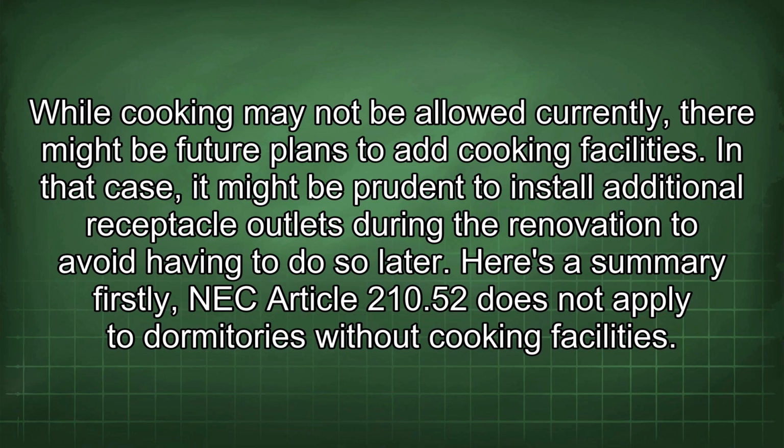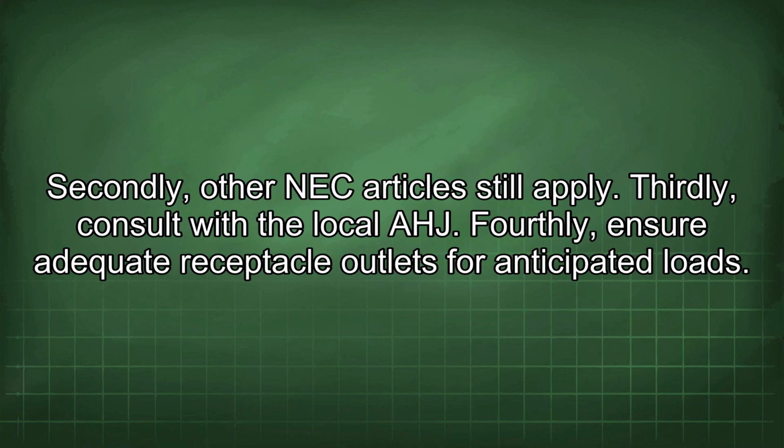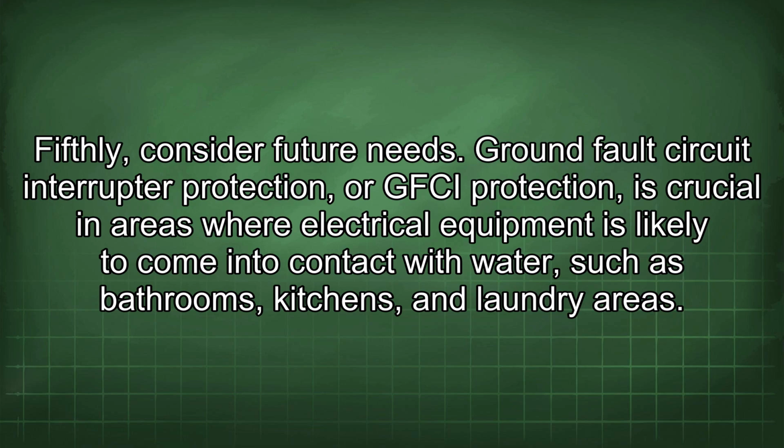Firstly, NEC Article 210.52 does not apply to dormitories without cooking facilities. Secondly, other NEC articles still apply. Thirdly, consult with the local AHJ. Fourthly, ensure adequate receptacle outlets for anticipated loads. Fifthly, consider future needs.